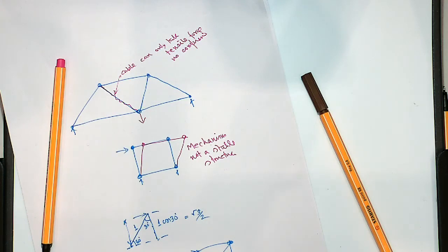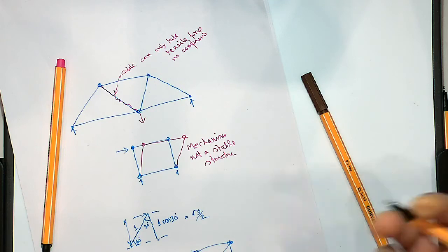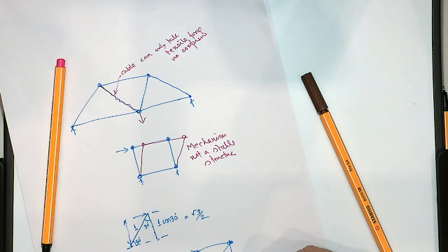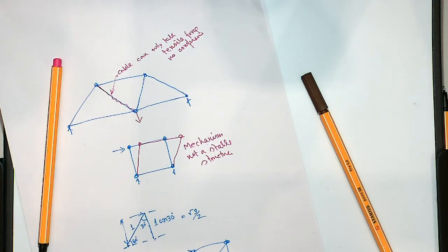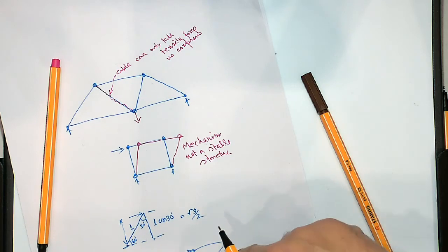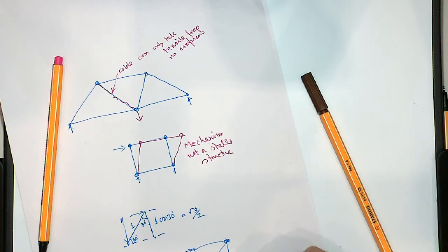But then on the other side, if you consider here, there will be horizontal and vertical reactions, so nothing else you could say is zero force. Well, if there's no support there, then it would be zero. If there is no pin but a roller, then that would be. Oh, so the second one's a roller then. Both are pinned, I put. So two reaction forces. What if the other one is a roller, then of course the horizontal member would be zero. So if there is nothing like this, then that would be a zero force member.